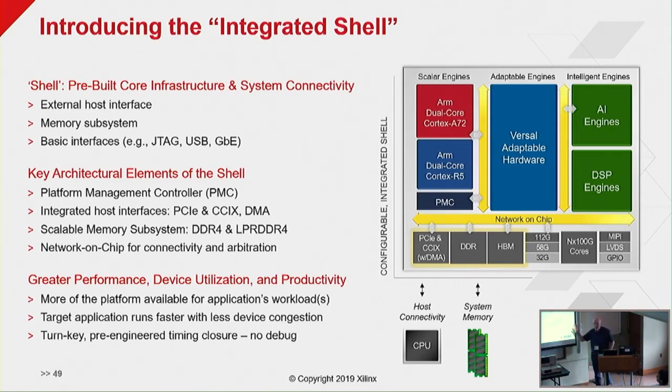The essence of this is that this part boots up without any bit streams. Okay, so it boots in milliseconds. The processors are up, the networks are up, the CCIX is up, the PCIe is up. So you don't have to have a soft shell here. We showed you that at the start with the Alveo cards. That goes away. The system is talking to the PCIe and the CCIX is up, and it's all ready to go. You can load the bit stream before that if you want to. You can load the bit stream after that if you want to. But this is a system that basically powers on, ready to talk to the world that it's connected to.